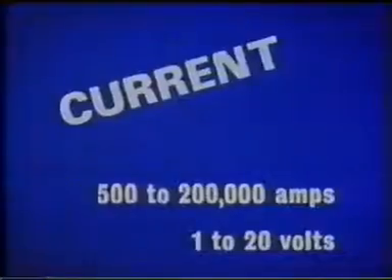A good weld depends on 3 basic factors: current, pressure, and time. Their effects are interrelated, and the ideal combination will vary to suit the component material and thicknesses. High currents are needed for all resistance welding techniques, though only for short periods, and peak currents of 500 to 200,000 amperes may be necessary, but the voltages used are low and are between 1 and 20 volts.